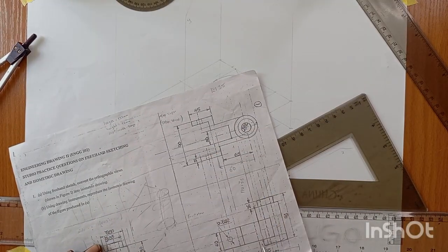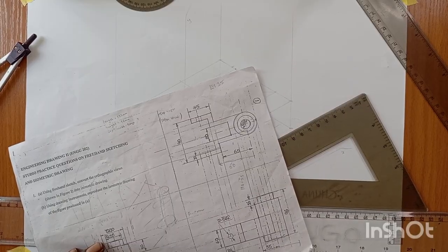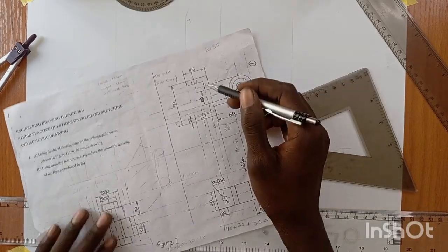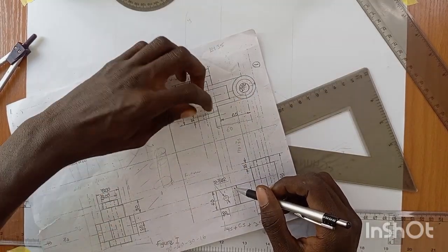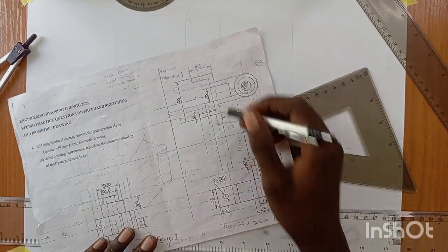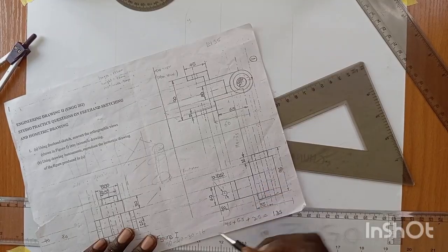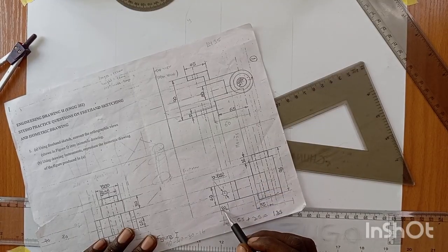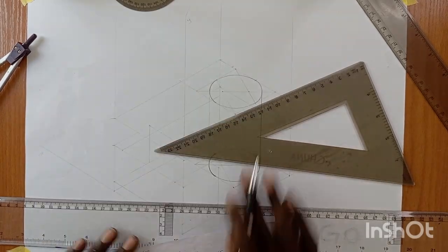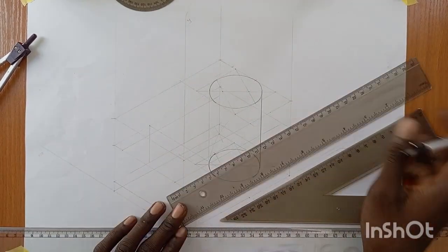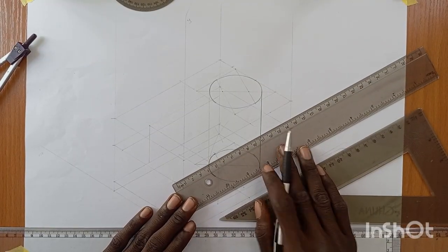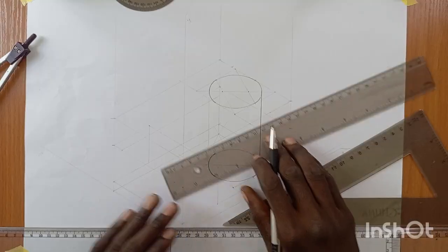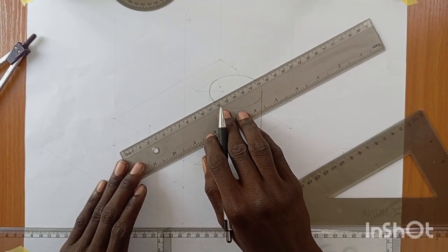How do we get that? What is the distance? So now, as you can see, from this point here, it goes downward, that is the hidden line here, as given. We know the inner length here is not given. So from here, this is the hidden line, it passes through here, you can see it. And from this edge to the center of this hole is 20, which means from here to here is going to be 20. The length inside is 40. So now we measure 40 millimeter from here, and then do the same thing for this one also, 40 millimeter here.